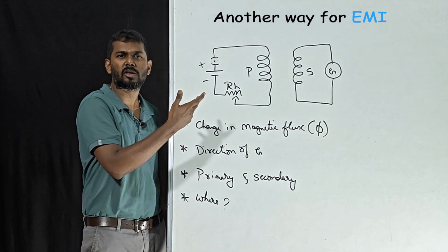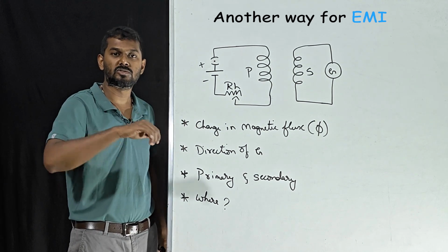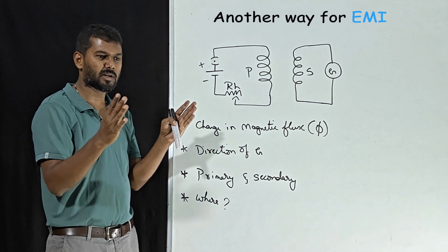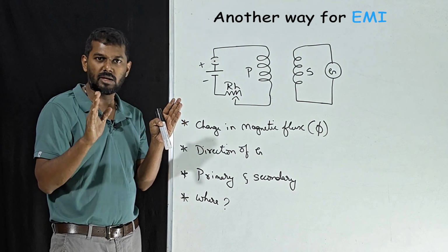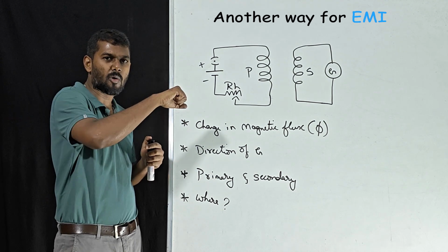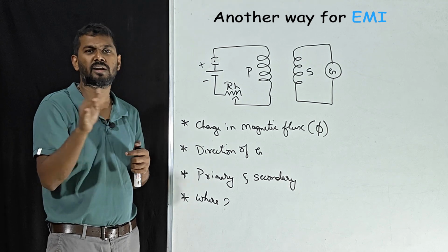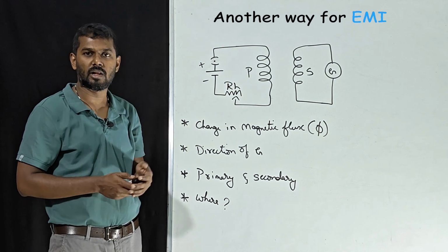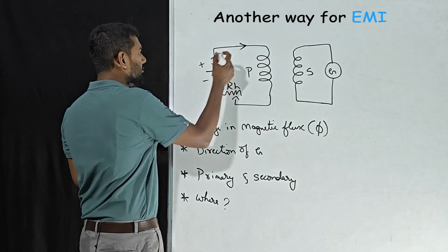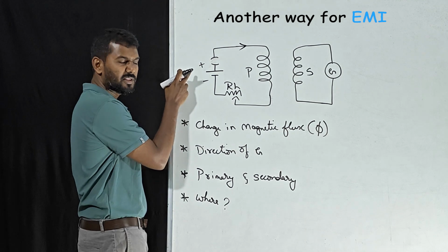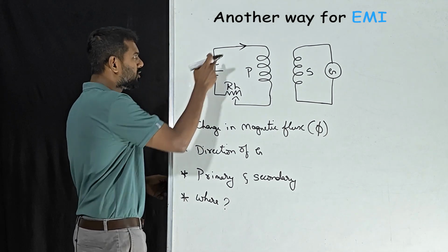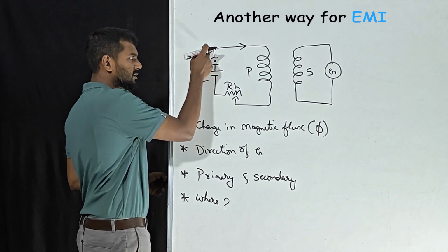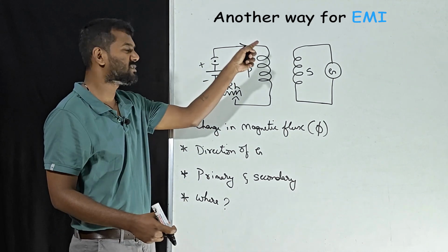The important thing here is the rheostat. What do you mean by rheostat? It is a variable resistor, so we can keep changing the value of the resistance. There will be a knob on the device. We have to keep moving the knob to increase or decrease the resistance. If the resistance is varied, the current in the circuit will also vary. Whenever there is no dot, it is an open circuit, current will not flow. Whenever there is a dot, that means there is a connection. This is a closed circuit, so current starts flowing.